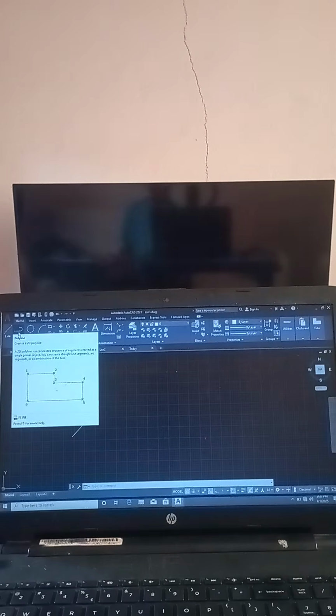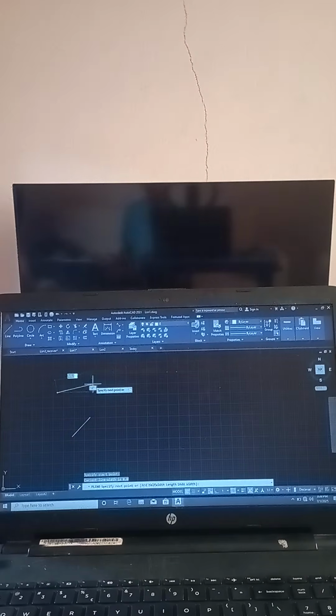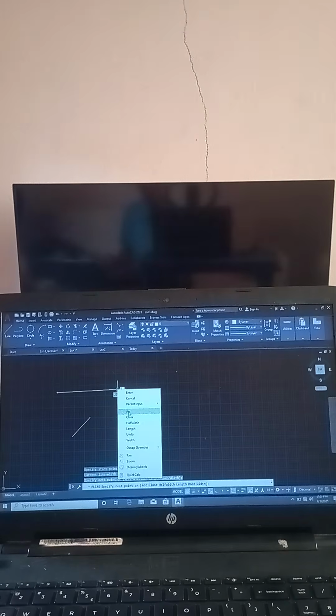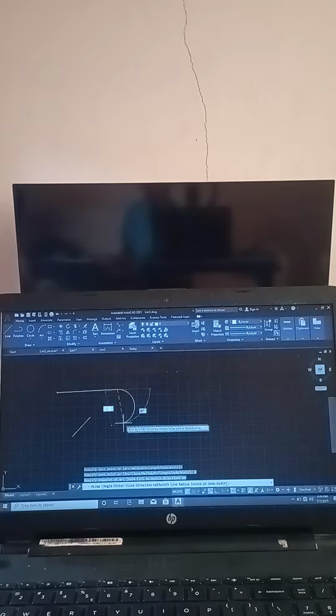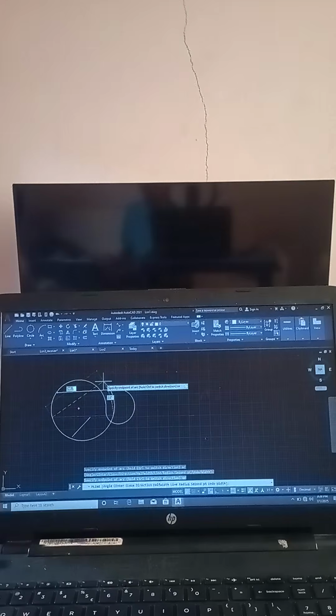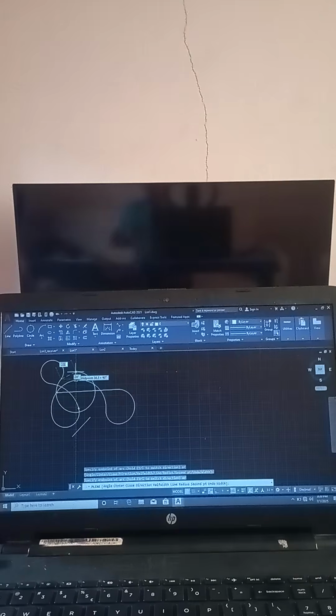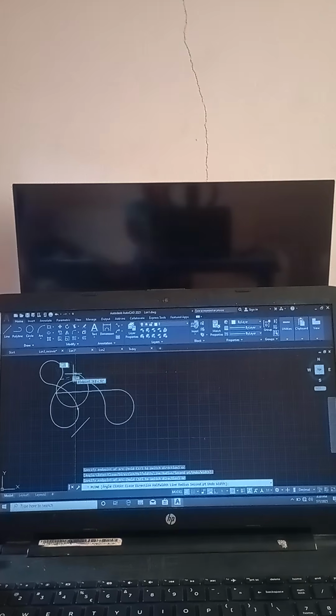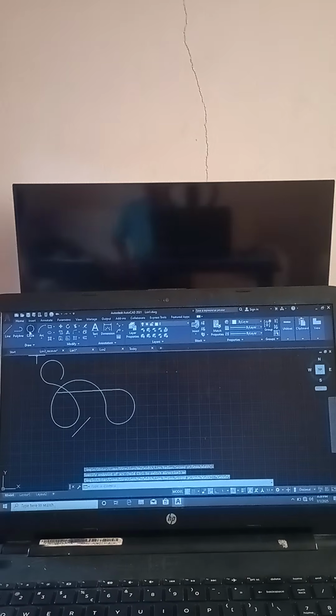That is polyline. One thing about it, it has arc at the end of it, and there are many things you can do with it. Let's just play with it now. You can repeat as I'm repeating. You can do a lot of things with the arc. Now this is for polyline. Whenever you are through with whatever you're drawing and you want to bring it back to normal, you press escape, and then normal.